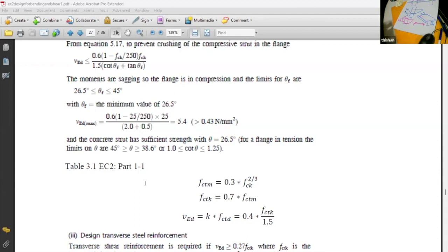But in case of inverted T beams that we use for foundations, this failure can happen. So it's not a situation for general slabs. Slabs we are supposed to check, but generally when you check for a slab it will be okay. If that is the case, what is the solution? Better write a spreadsheet so that this will be checked automatically, because this is a useless calculation for most of the slabs. But you have to get these moments fed.